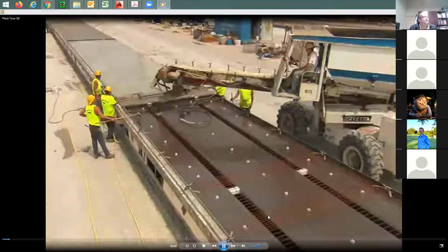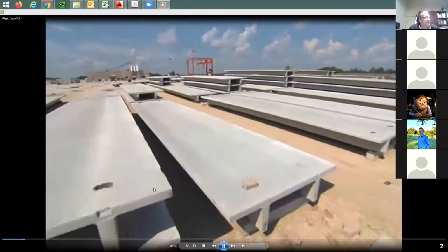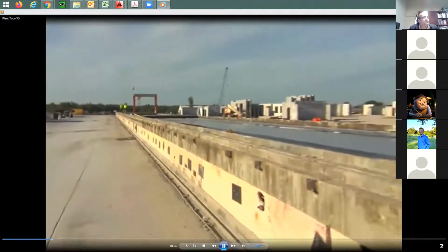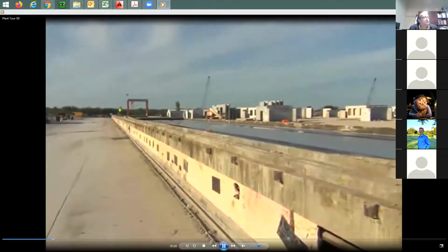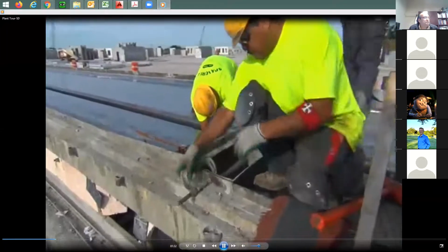Prestressed concrete unit at a pre-stressing plant. In this case, a double T. Here's a double T, it is 120 feet. Forms may be fixed with an appropriate draft to allow for easy stripping. Once the bed is cleaned, it's ready for setting up today's cast.